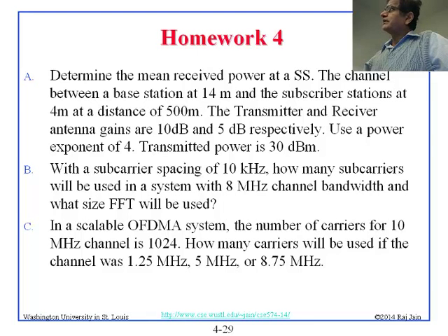Now remember, everything that is given to you in dBs, you cannot multiply or divide in dBs. So you have to convert that into ratios when you multiply. dBs only add. If you have to add, then you add dBs. But if a formula calculation requires multiplication or division, that means you have to convert.